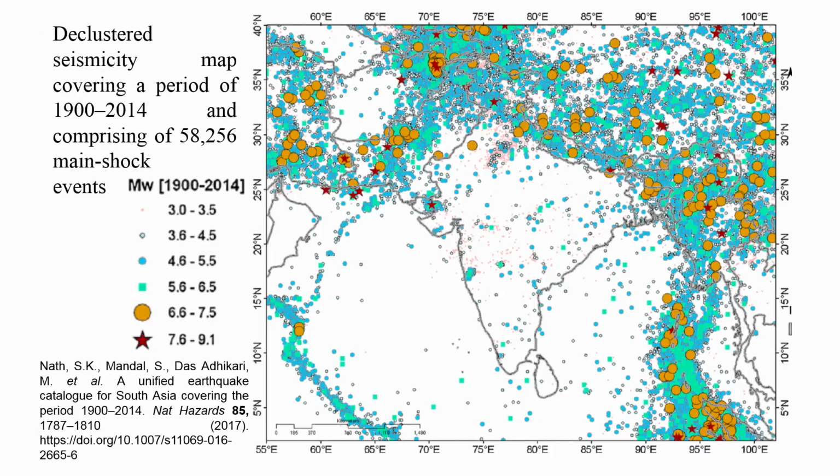These people published a map, okay, a seismic map from 1900 to 2004. You can see here the legends used. In almost all of southern India, okay, the entire part of southern India, this is the peninsular India, your highest reported magnitude is only 6.5. Okay, so there is nothing beyond that magnitude. The red dot is exactly 6.75, that you can see mostly on this part.